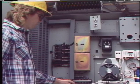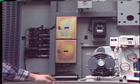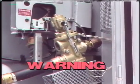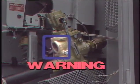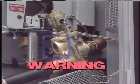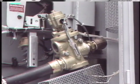When pressure is restored, the mechanism can be operated to determine how many times it will operate on a full tank of air. A warning is needed here. When a pneumatic mechanism operates, air is released through an exhaust valve or port with considerable force. For safety, keep the area around the valve or port free of loose objects and stand clear when operating the mechanism.